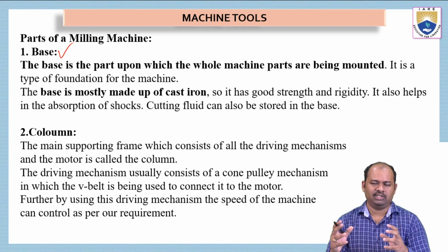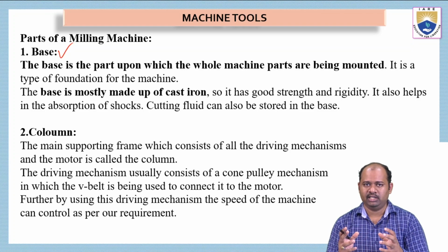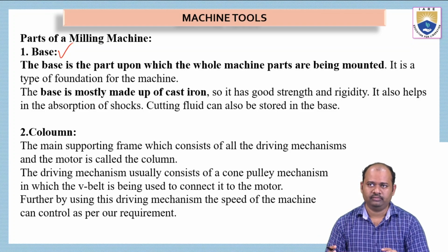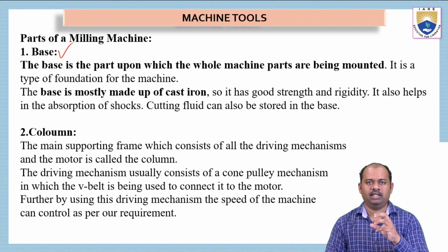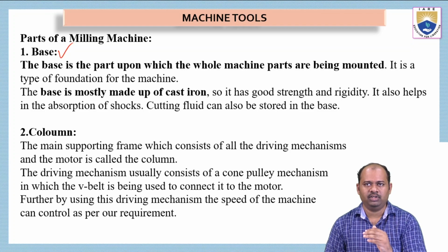So it has good strength and rigidity because it is cast iron. It is very heavy also. It also helps in absorption of shocks. Cutting fluids can also be stored in the base. So the base is so huge that it can be used for a functional purpose. It is not only a solid base, it has openings or shelves where we can put cutting fluids also.